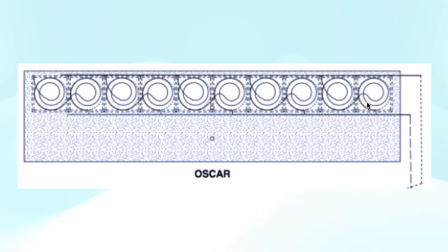One last thing that may be easier to see in the drawing as compared to the video that we were showing. You can see here you have these coils. You have a connection from this line. Let's just go ahead and call this the supply line. Like I said, it doesn't matter so long as you hook up the coils correctly, but let's say you have the supply line here, so you have a connection from the supply line to this first coil. The other end of this coil is hooked up to the coil next to it, and the end of this coil is hooked up to your flush line. So you have 2 coils paired together, and these 2 coils together have one connection to the supply and one connection to the flush. So long as you do that, it doesn't matter if this is the supply and this is the flush or vice versa.